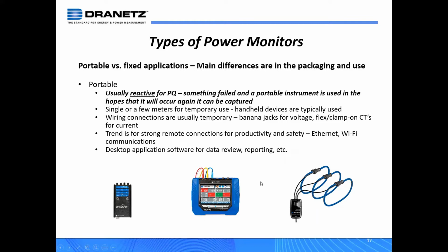And then you also have what we call power analyzers. The difference between the two is that a power analyzer is going to perform all the functions in terms of power monitoring that a data logger will do. But in addition, it provides data analysis. So once I record these power quality anomalies, I now need to analyze that.